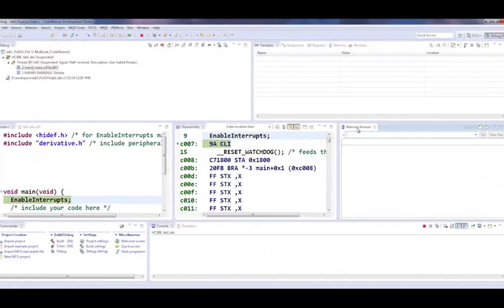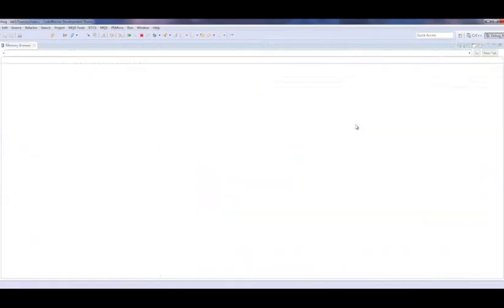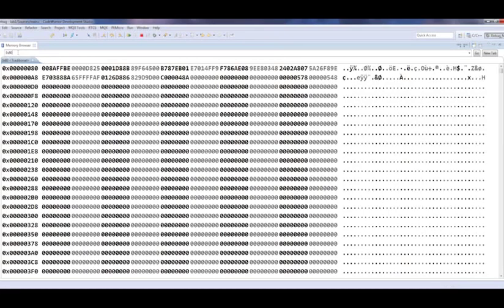Now for Lab 2, we're going to be examining memory, and we're going to be using the memory browser. And as before, we can just double click on one of these and make it go full screen. And since we've changed our font size, if we do 0x80, which is where our RAM is, if you look at the lab, you can see that it's showing everything that's physically on the board, but it's not showing it in the way that we want.